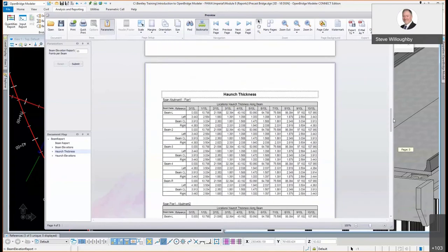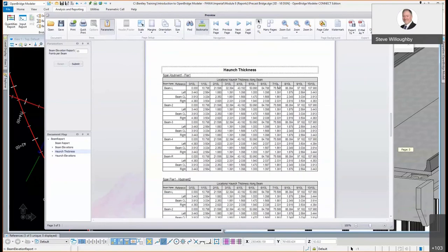And so you'll notice, just to point this out, again, when these beams were defined, we used a 1-inch minimum haunch, or 1-inch minimum thickness, and a 3-inch camber. And so for the beams on the left side of the deck template here, right here at midspan, there's that 1-inch value for the left edge of flange, because that was the controlling location.